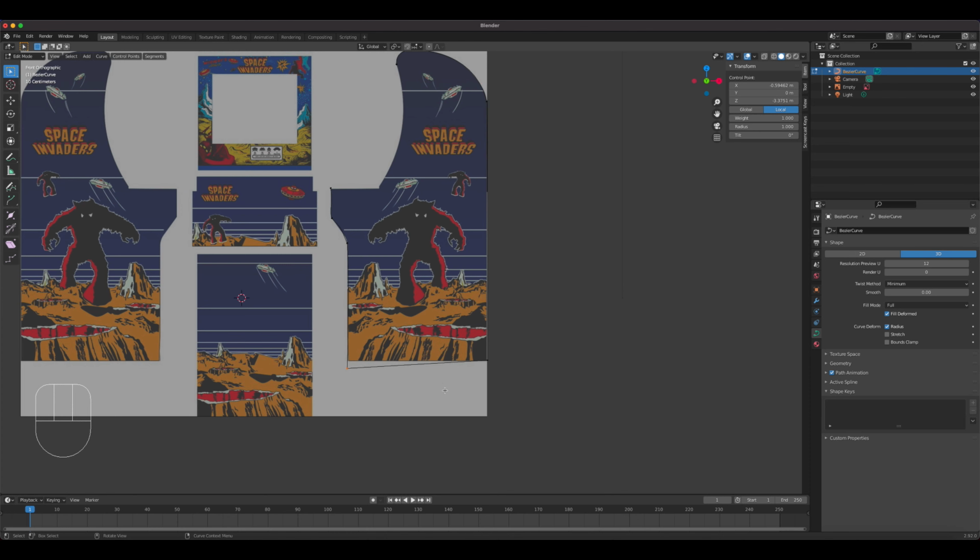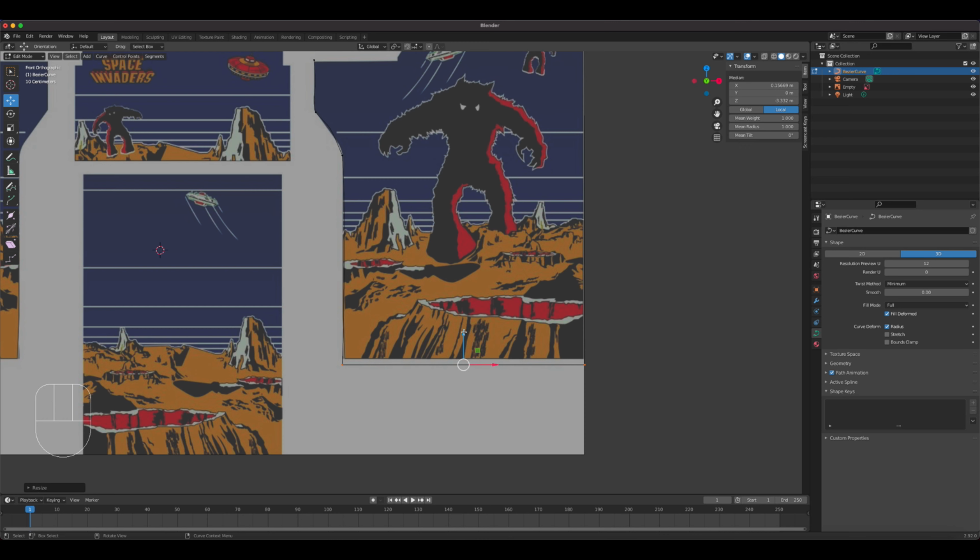Same thing with this. This is the z-axis, so I'm going to press S, Z, and 0. Oh, forgot to select it. There you go. S, Z, 0. Okay, and then move it, so you know for sure those things are aligned, so it's flat right there. All right, same thing with this one. It's these three actually, not that one. So that would be S, X, 0, and they're all lined up.